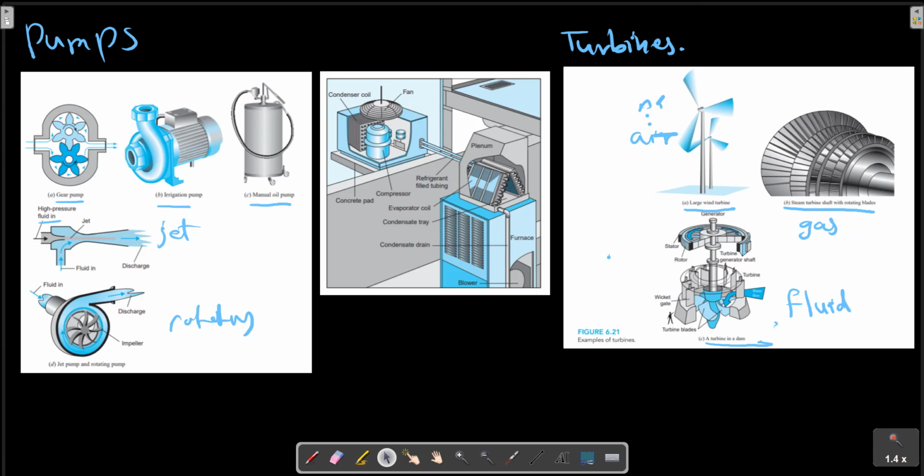In cooling mode, it has two heat exchangers, one inside that cools the inside air and one outside that dumps energy into the outside atmosphere. This is functionally the same as what happens in a refrigerator. The same type of system can be used as a heat pump. In heating mode, the flow is switched so that the inside heat exchanger is the hot one and the outside is the cold one.